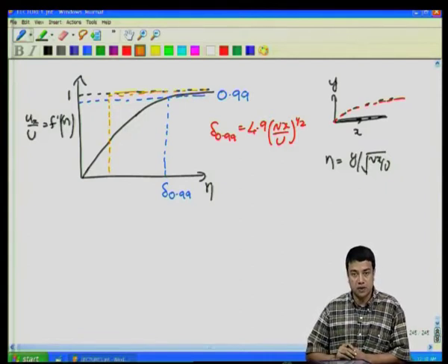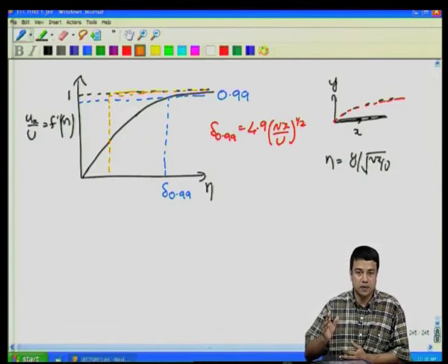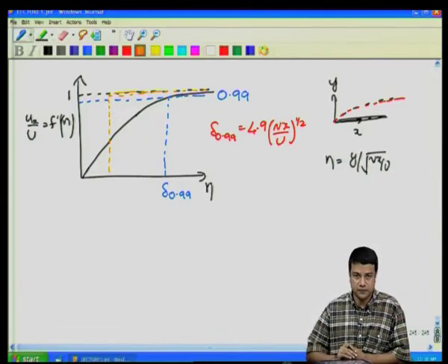That is what the outer potential flow is going to tell you, because the outer potential flow just predicts that the velocity is equal to capital U all the way to the surface. However, because of the no slip condition at the surface, the velocity decreases to 0, and because of that there is a decrease in the flow rate. That decrease in the flow rate is written as rho u times delta, where u is the mean stream velocity.